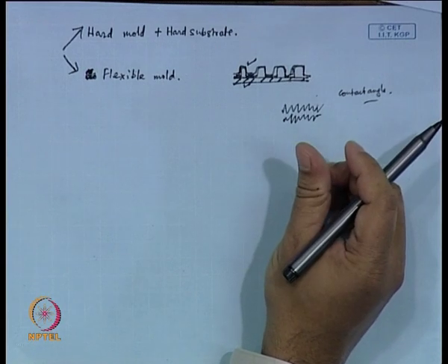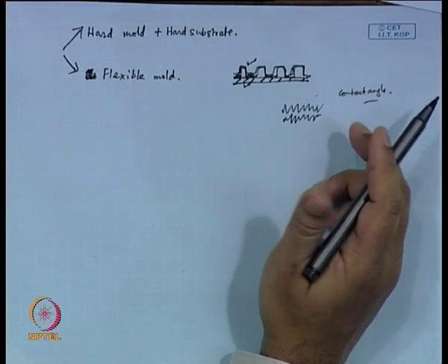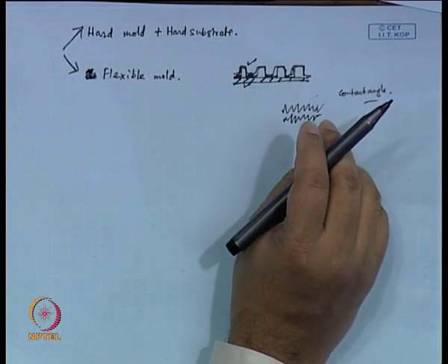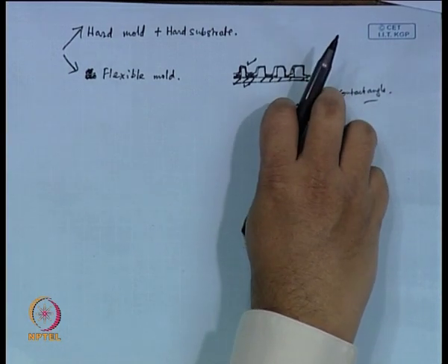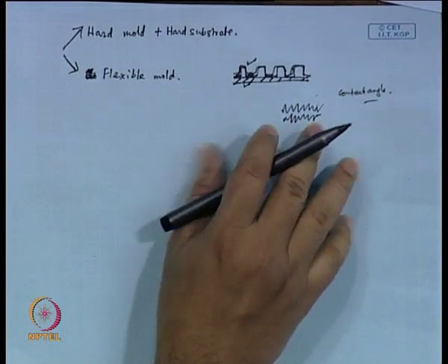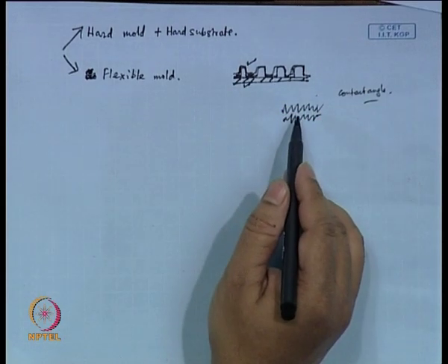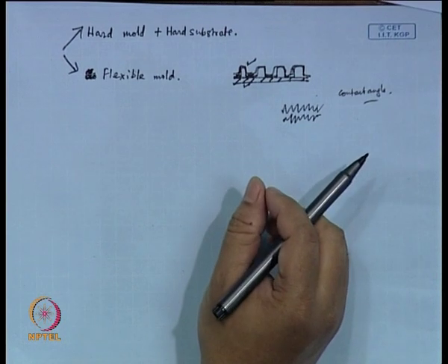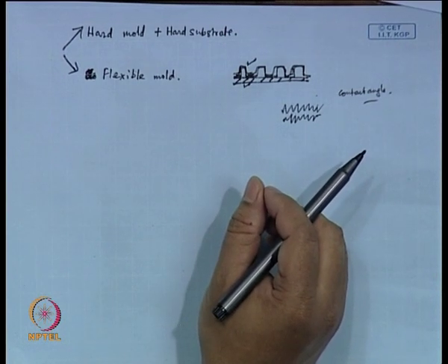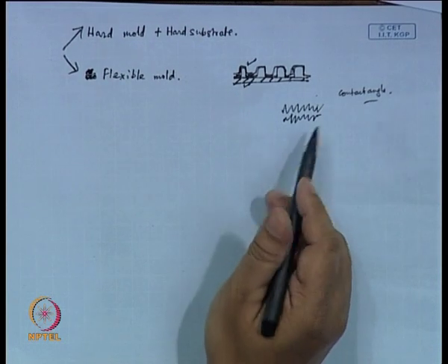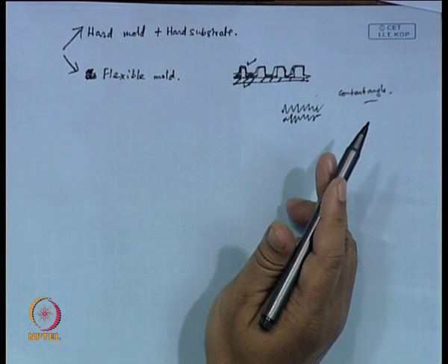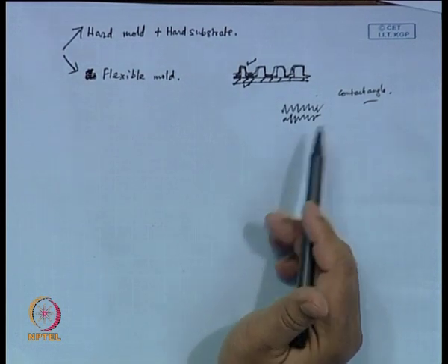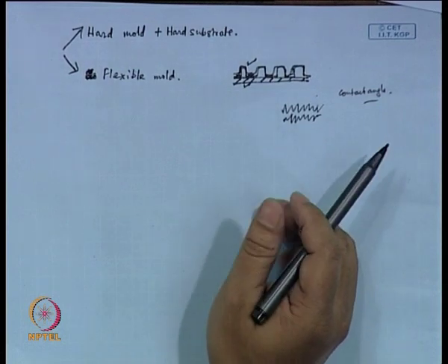So, a soft mold can achieve what we call conformal contact. You can achieve it by pressing them hard. That is possible. However, if you press them hard, if you are ready to put that much effort into this, then you may as well squeeze the liquid into it instead of depending on the capillary phenomena to go everywhere. You can just squeeze it.